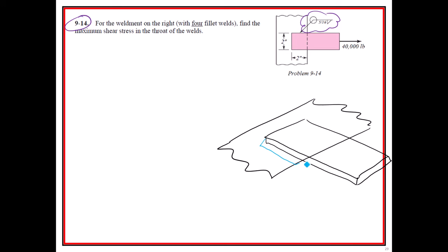And what does that mean? Well, we have this weld right here. That's the one that we expect, and still over here, right on the back side of the thing. But we'll also have a weld that comes back and looks like this right here onto the side, and also underneath this, right? Because that's what that symbol means, all the way around. And we only need to have 1/2 of that thing, because we're saying that it's welded all the way around. So it actually has a weld on all 4 sides.